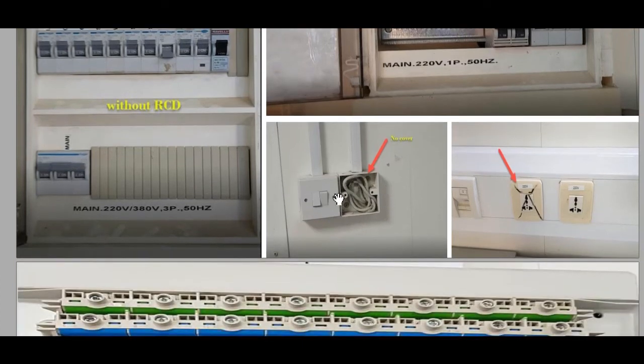You see here, for example, there is no cover, even if there are no stripped wires, but a plastic cover must be made to cover this box. As you see here, we have a broken or damaged socket, which must be changed. All this you will record as a punch list during your primary visual inspection.